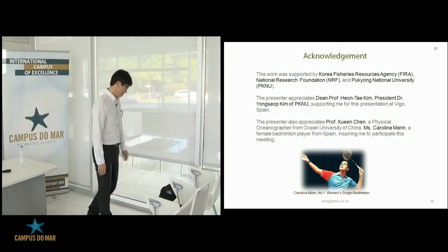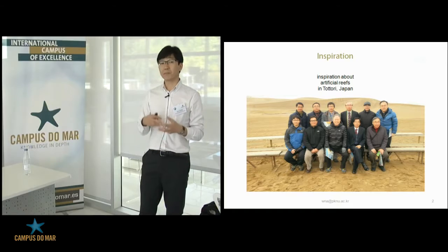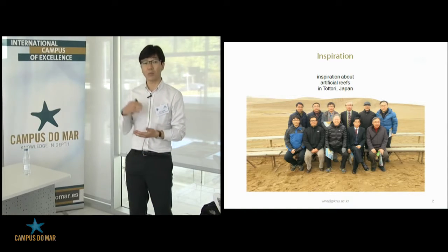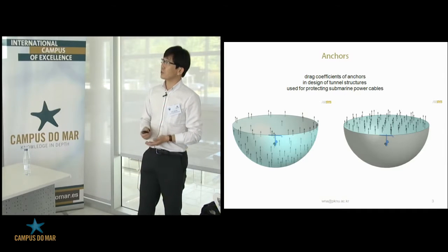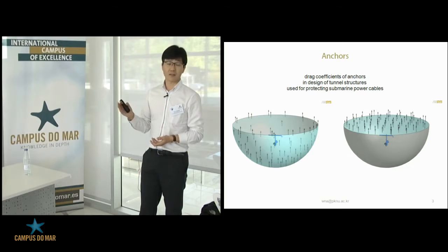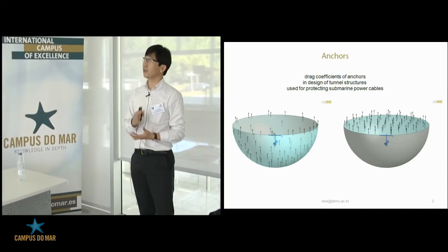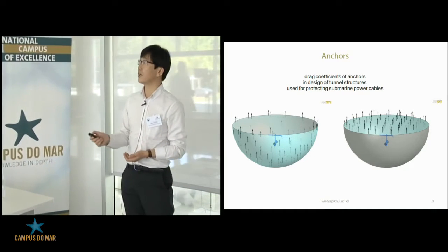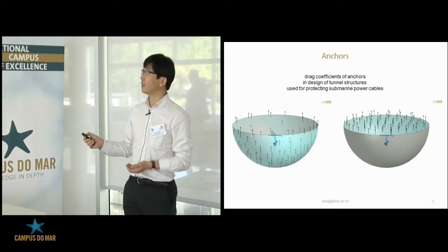Artificial reefs on the seabed experience many hydrodynamic forces. So it is very important to know drag coefficients to calculate sliding and overturning, those things. At that time, I used to calculate drag coefficients of anchors in the design of tunnel structures used for protecting submarine power cables, using some numerical schemes here. They put the anchors and then some inlet and outlet.